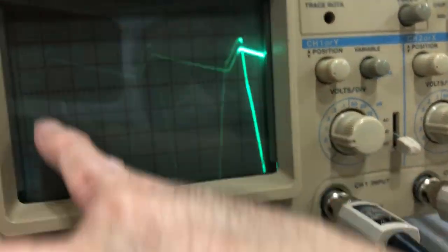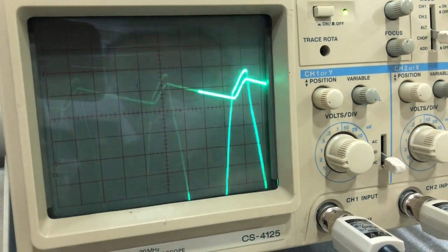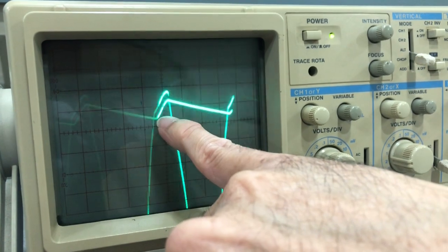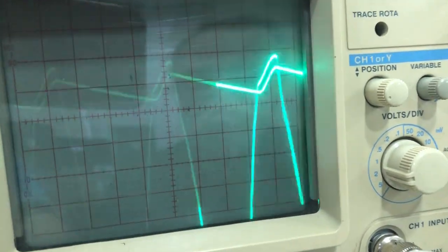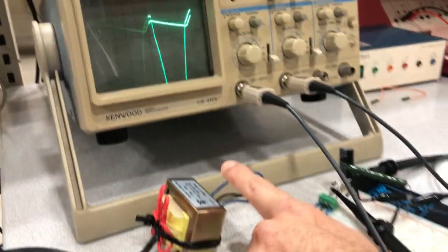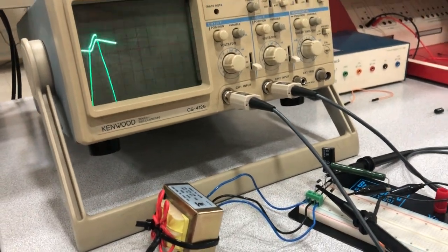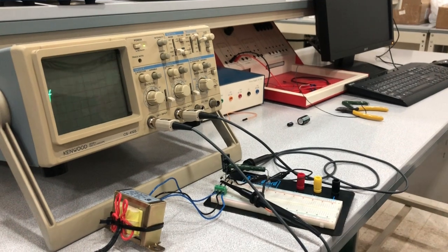The signal is charging during the positive alternation and discharging in between. This is a half wave rectifier. Notice the current of the charging is distorting my input sinusoid. It's not perfectly sinusoidal anymore. This is real world, because the secondary here has a resistance due to the winding. The copper winding is thin, it's not very thick. Everything has internal resistance.